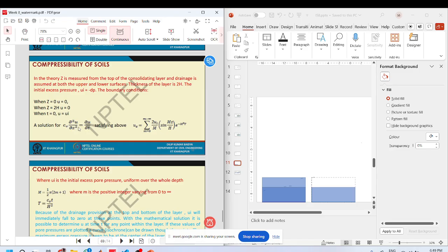And in the heat equation, you have a thermal conductivity concept. So basically, the rate of dissipation of your water pressure or the flow of the water through the sample is a function of permeability of your material multiplied by the spatial variability that is given by your continuity equation.